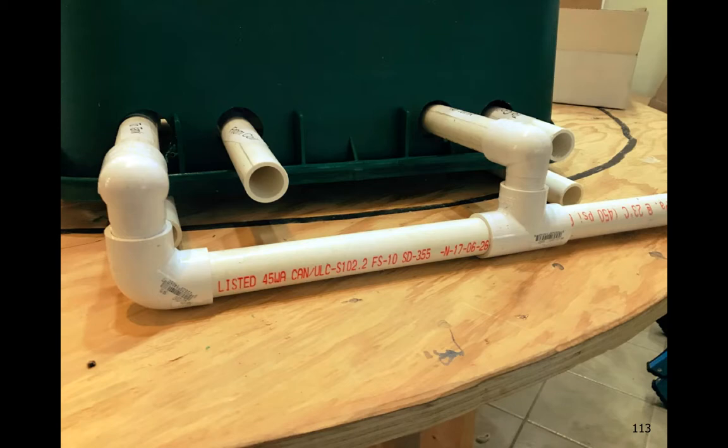And then in the kit, we're going to have the two tail pieces that are labeled to tank. They're going to be connected together this way. We've got a couple of street L's, an elbow and elbow and a T, and then it'll go off to the left in this case, and that'll be hooked into our 4x1-inch T on the sewer stub coming into the septic tank. Our other two ports sticking out there, again, those are going to go to our low flow basin.